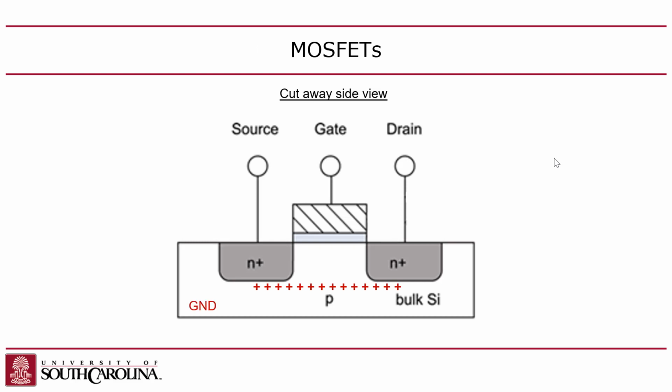Okay, so basically, this is what I just got done explaining. I put VDD on the gate, which puts a positive charge. Now this is a little confusing because I have plus signs here, but that plus sign is meant to represent a charge. These plus signs are meant to represent charge carriers. These pluses are not the same as those pluses, right? But anyway, I put a positive charge, and then that attracts the minority carriers, which are the holes in the channel, and the current flows, right?